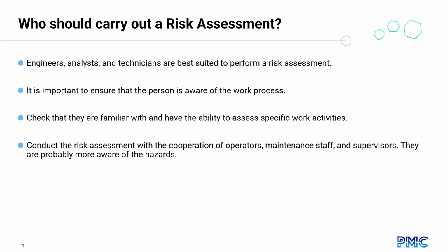And generally, the people who are most familiar with the operations are the operators themselves, the maintenance personnel, and plant supervisors. So it's advisable to ask these people questions, to interview them, because they are the ones who are most aware of the hazards in their workplace.